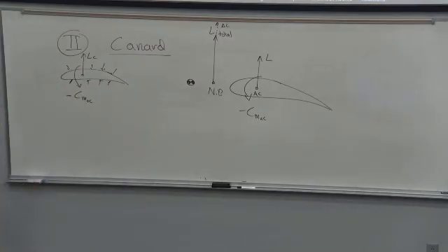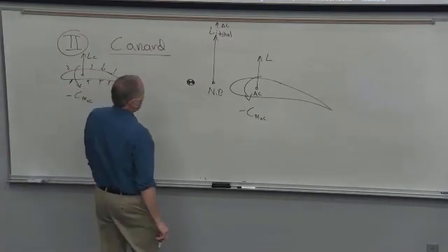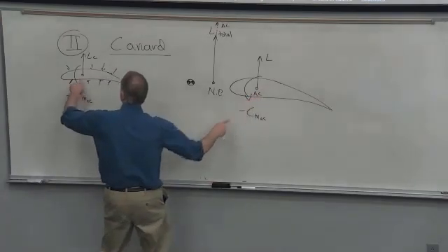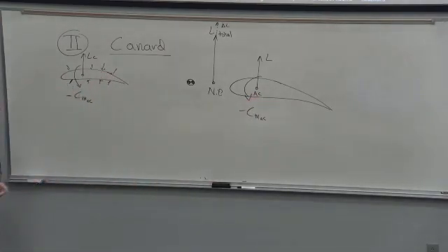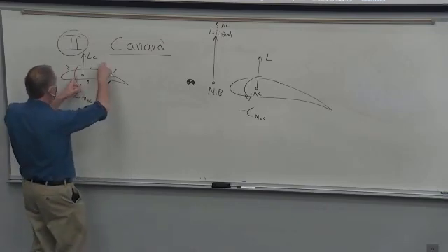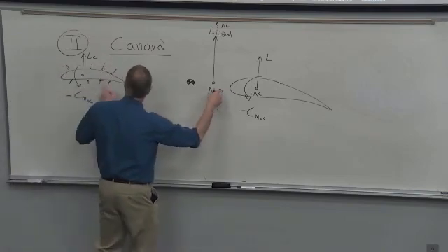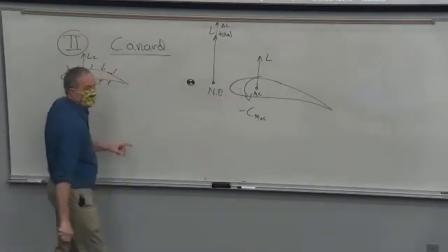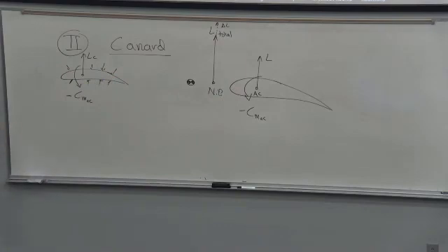And one of the advantages that they talk about here is that very often the wing and the tail both produce positive lift for all of the flight conditions. With the horizontal tail, sometimes the horizontal tail is producing uplift and sometimes it's producing downlift. And that downlift takes away from the lift of the wing. So there's some efficiency there. And there's also some effect of the wake of the canard hitting the wing that has some positive or negative aerodynamic effects on the wing. You have to do it right.